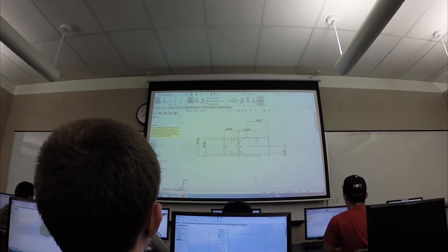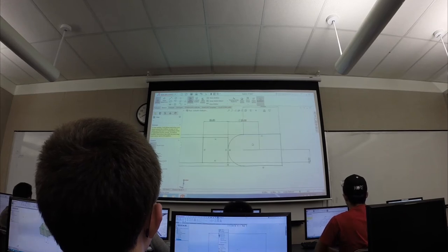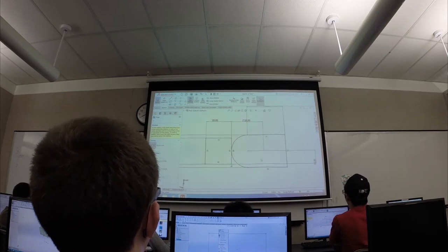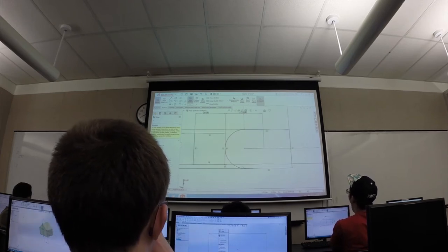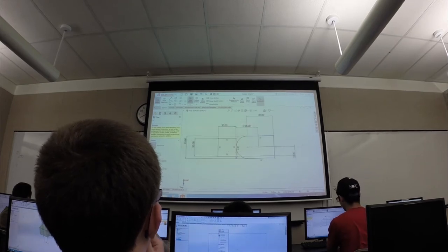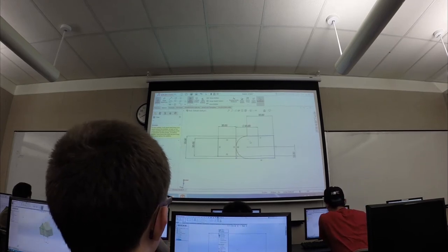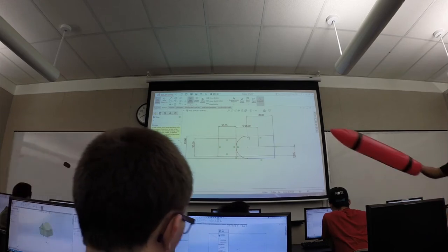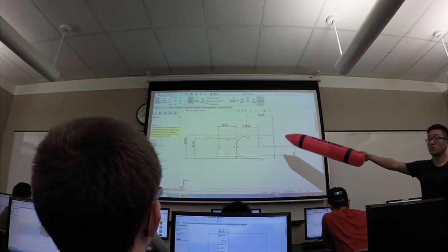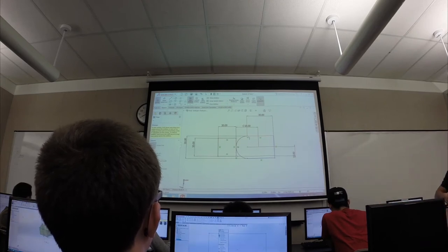So now you're left with this. But you notice that your box, or what used to be a box, turned from black into blue. The reason for that is because earlier we defined the vertical dimension of this box on that line that we just got rid of. So when you got rid of that line, the dimension also disappeared.